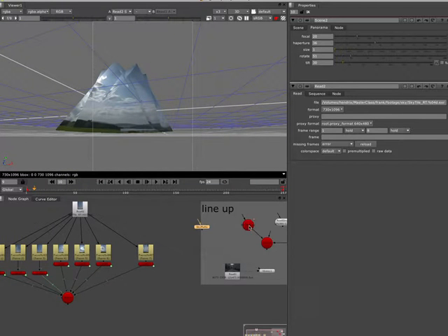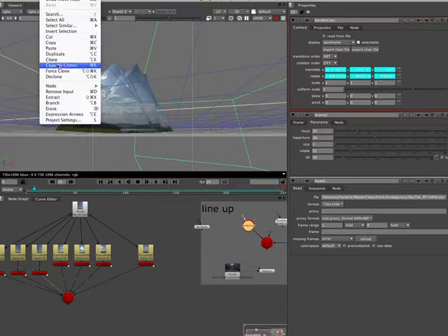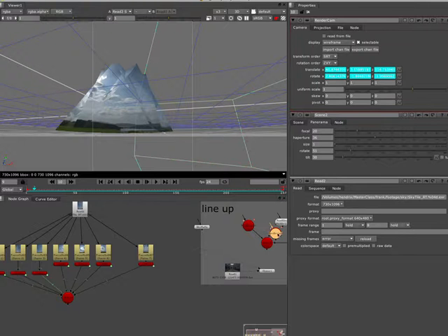Now I'm going to grab this camera and I'm going to clone it. And like I said before, I need to check that I'm not reading from file before I clone it, because it's an FBX, and if you read from file, that is one of the gotchas, right? So if you're cloning a camera that's reading FBX from file, not so good. So I'm going to clone it, edit, clone, and it's Command K. I think it's Command K.